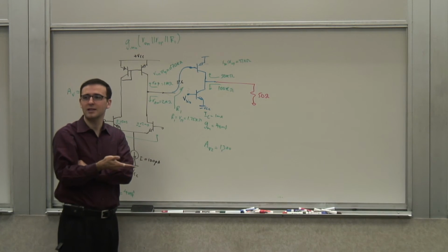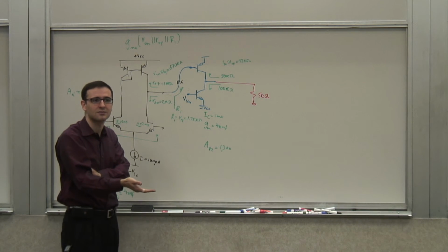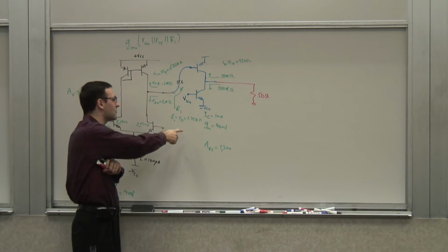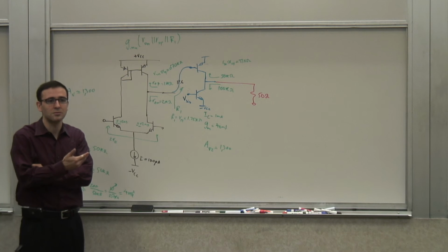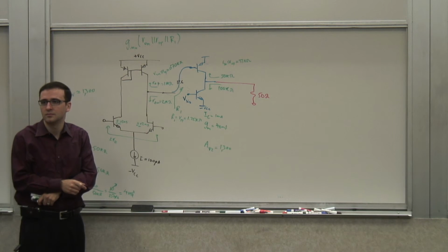So probably I need another one. I need probably 2, right? I want to get this multiplied by beta squared. If I get beta squared, that gets me to about 10 or 12 mega ohms, which is good because then it wouldn't load this guy too much. Fair enough?